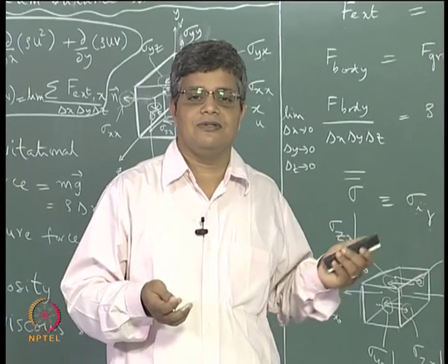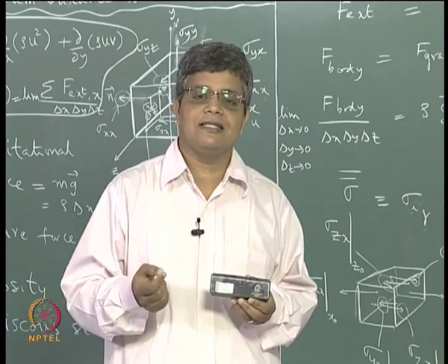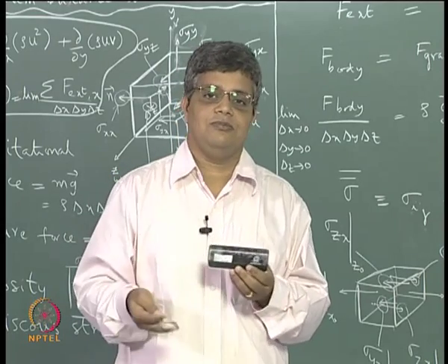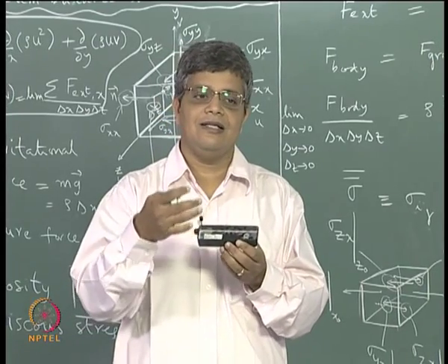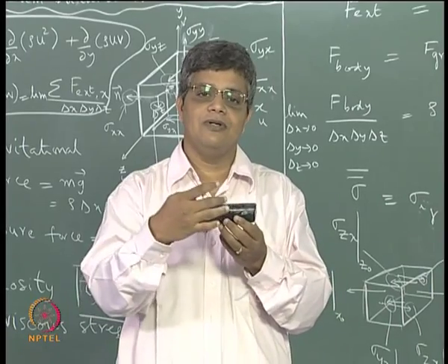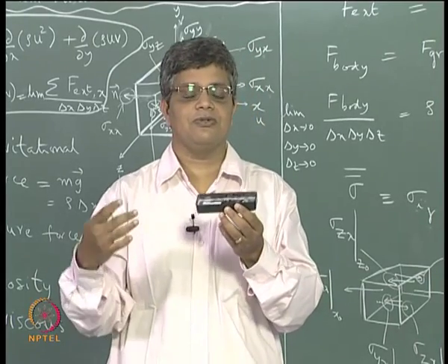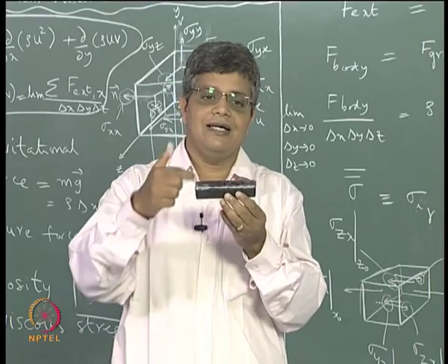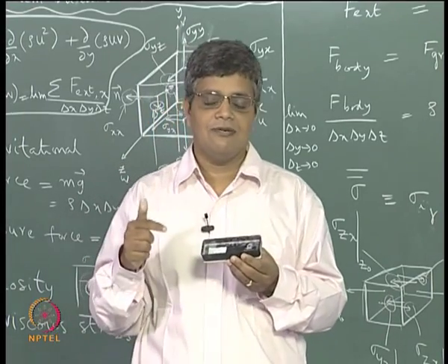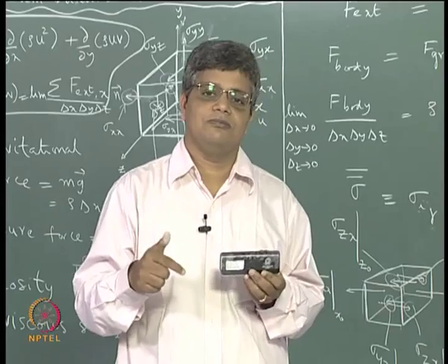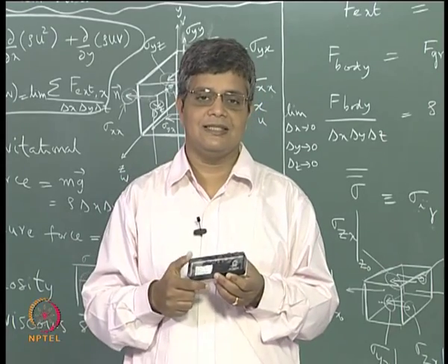and why it is the rate of strain is something that we have to see, because fundamentally a fluid is different from a solid in the sense that a fluid will continue to deform as long as there is a stress acting on it, whereas a solid will deform initially and then it will reach a condition of equilibrium with the force applied on it, so that you have a distortion which comes into equilibrium with the force that is applied, whereas a fluid by definition is something that continues to deform as long as the force is applied, and which stops deforming immediately as the force is taken away,